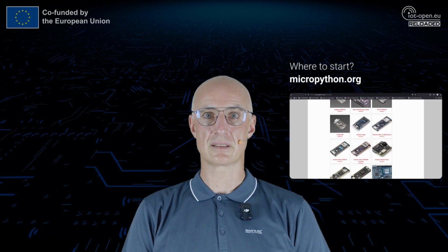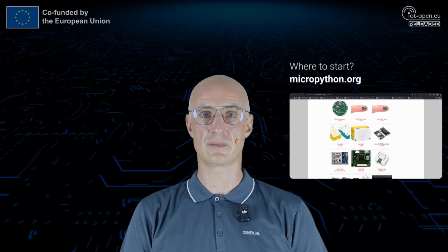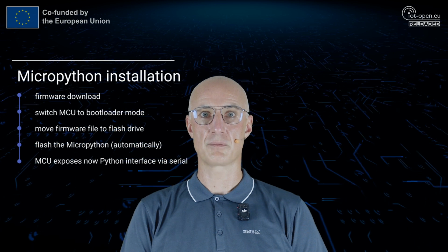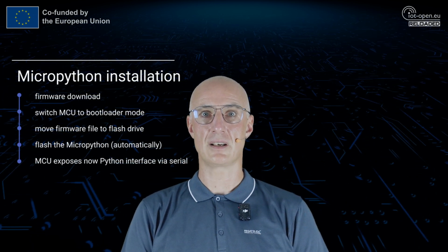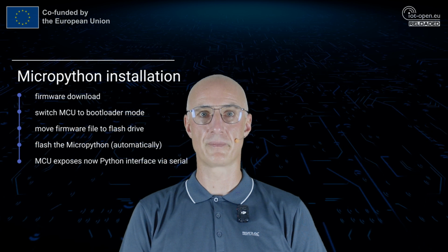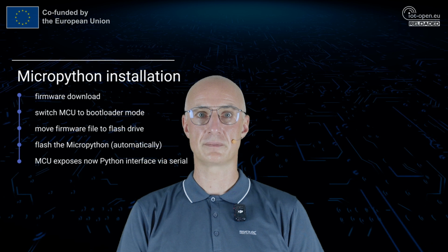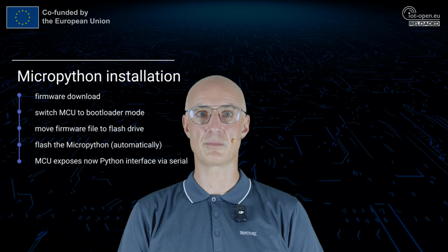Installation of MicroPython can be specific to the hardware, but it is quite common for the majority of the IoT MCUs. A sample MicroPython installation procedure for the Raspberry Pi RP2040 consists of downloading the firmware in the binary form, switching the MCU board into the bootloader mode that exposes a flash drive, and dropping or copy-pasting the file to the flash drive. The device automatically detects the firmware, then starts the flashing procedures and finally reboots.